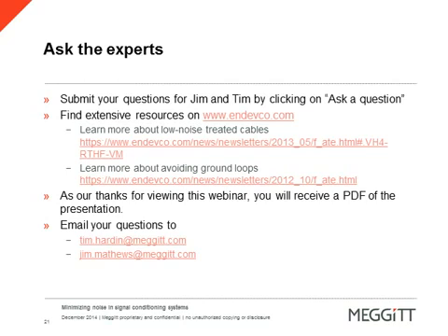Yeah, this is almost identical to what we just spoke to as far as the case design. Remember, when you have an isolated shield accelerometer, there's two ways to look at that. You could mount that directly and hope that the isolation on the case is adequate, but if you do have an electrostatic field or stray capacitance, there's a path through that case to the input side on the crystal inside the accelerometer. So it does then have a path back. It does provide isolation, but if you have electrostatic or capacitively coupled noise, it's not isolated from the ground on the mount.